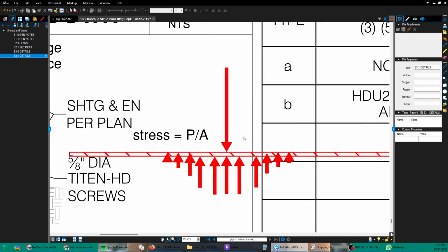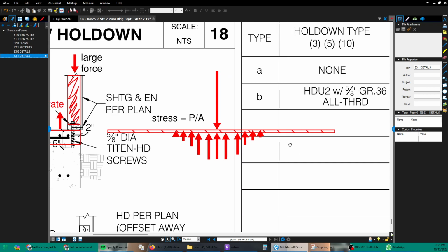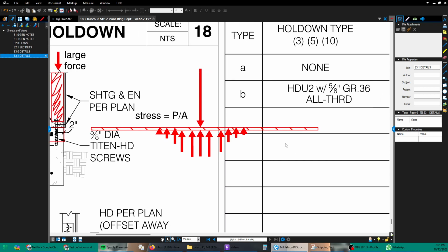And this can also work both ways. So I'm showing here a point load coming down and then the slab edge or the foundation having to distribute it outward. We could also have clay, expansive clay soil that expands when it rains outside, and it could expand unevenly due to where the rainwater collects against the foundation.